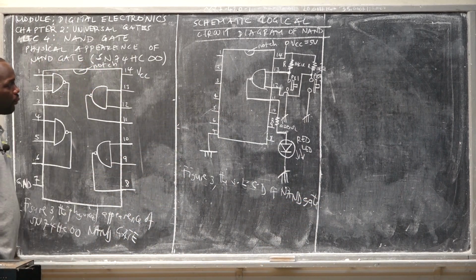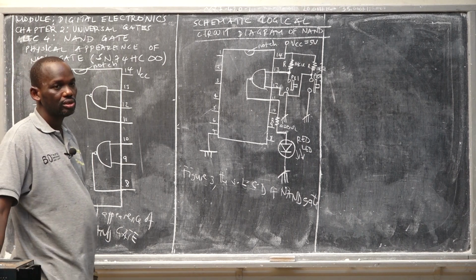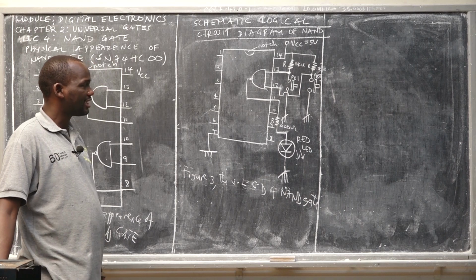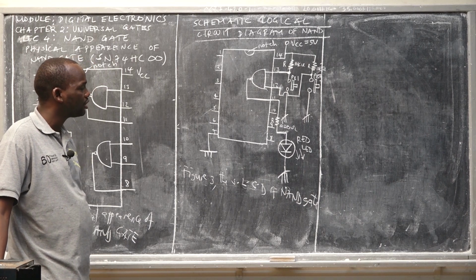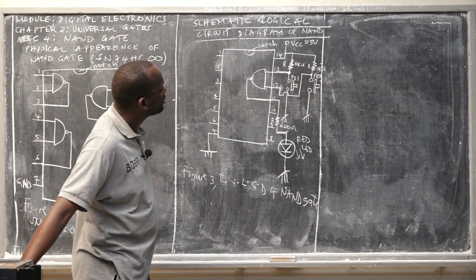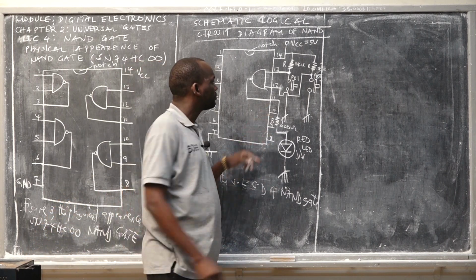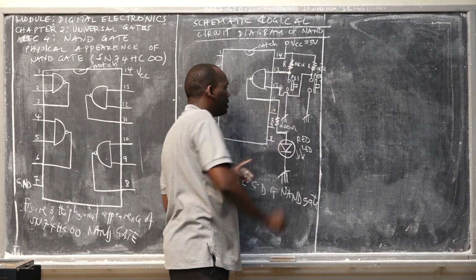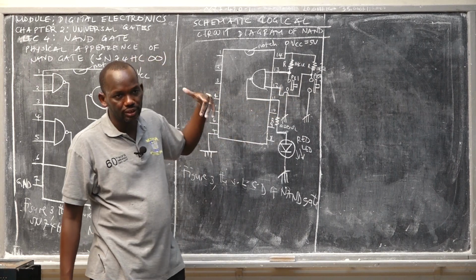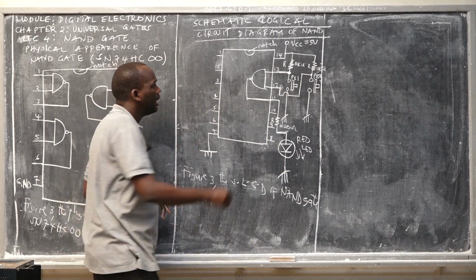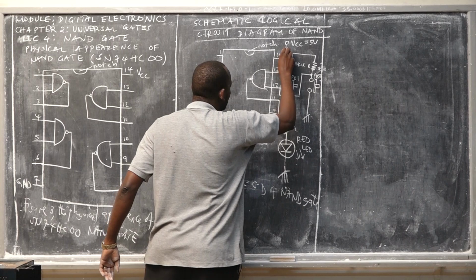How does this circuit work? It just has 2 principles, but you can clarify them in 4 principles. For the first state, remember that if the push button is not pressed, the voltage across the push button is 5 volts. That's very important.